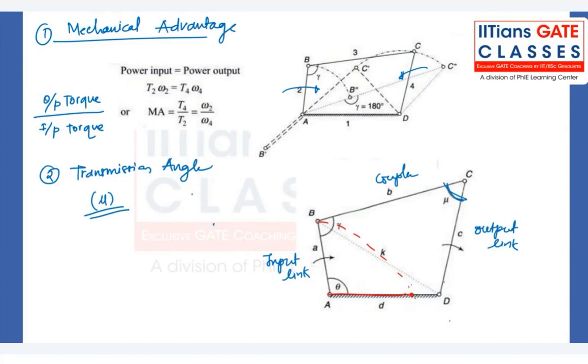So this is our link A here, overlapped, and now we'll have a link B which is a little bit longer. So it will turn to this side, and this is our link C. Now, if I rotate link A clockwise until it falls on the horizontal surface, then we'll get the smallest transmission angle, right? So this is the smallest possible transmission angle, mu minimum.